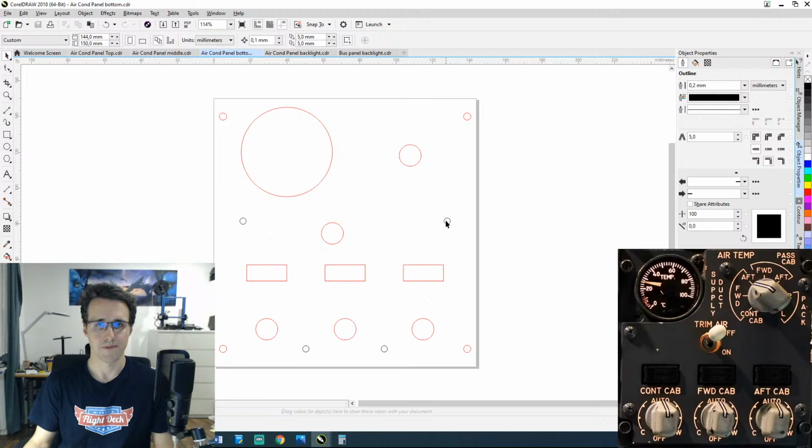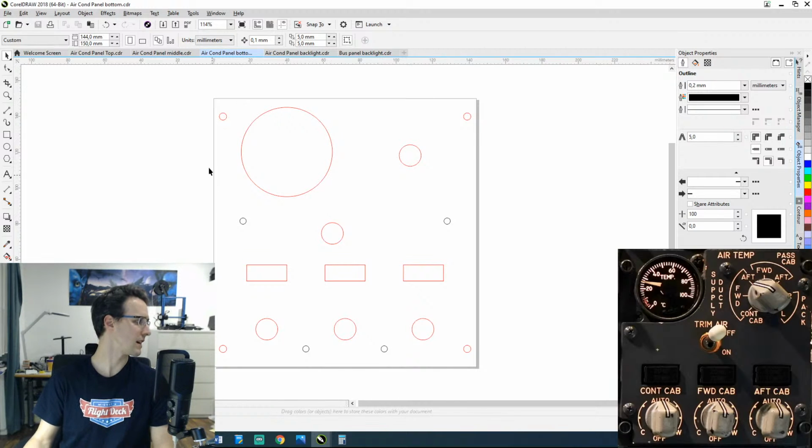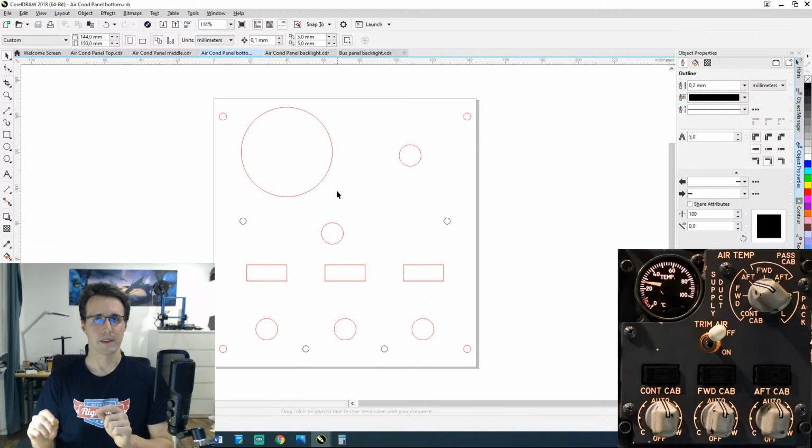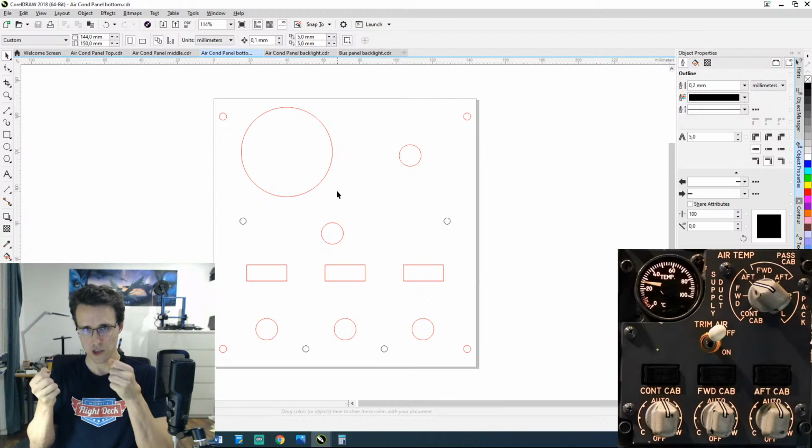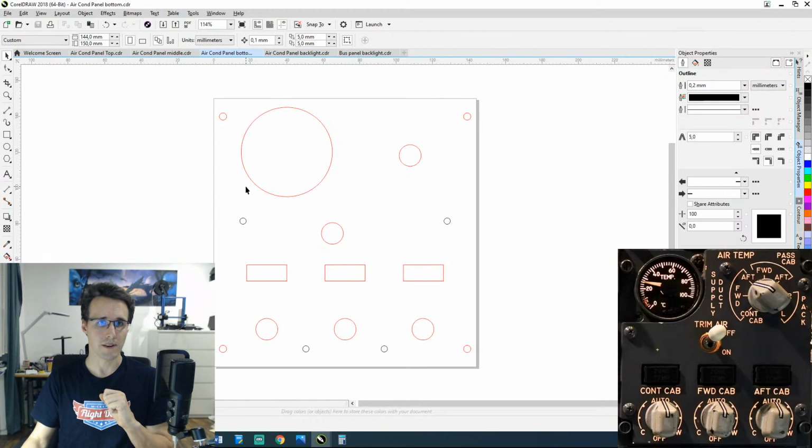Just cut out some other 3.5 millimeter holes to mount this gauge, and just 2 of them. I make them, I think, at these corners, or this one. I always forget. At this one. Here and here will be two holes to mount the gauge to the panels, and the other ones here and here won't be in the panel.